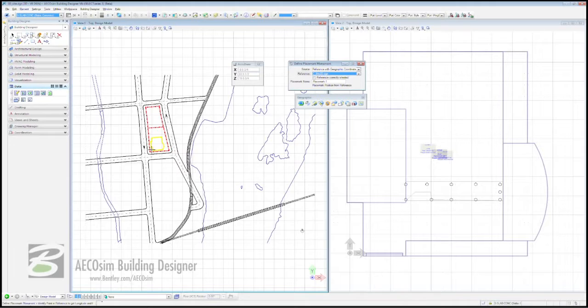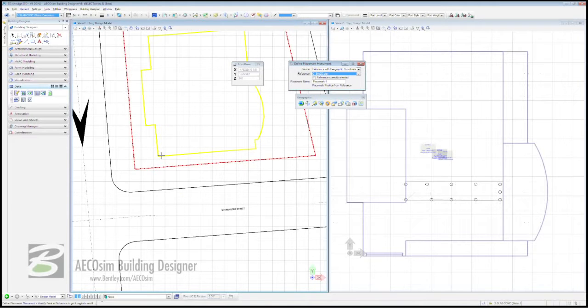because what we're going to do now is zoom into the footprint of the building, which the surveyors and civil engineers have kindly laid out for us. We're going to place a tentative point at the corner at the bottom left. And now we're going to place that monument point on our structure. And by doing so, we're going to be placing it and imbuing our model with georeferencing data.